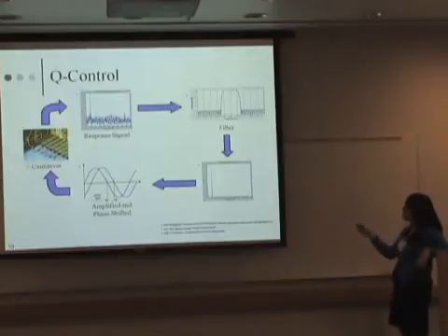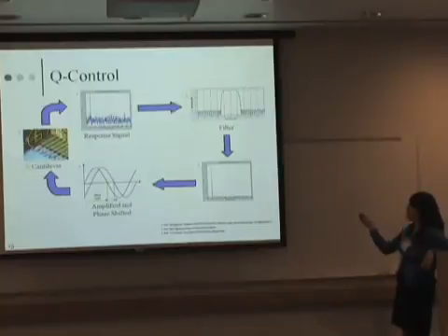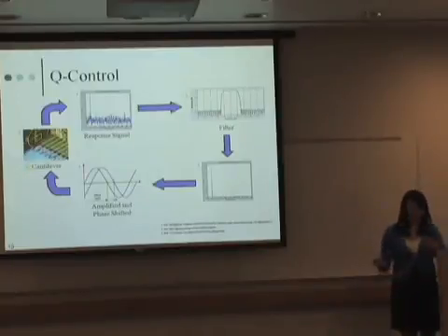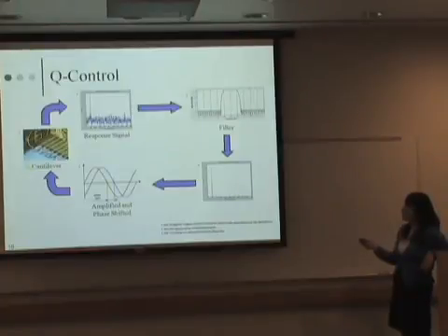So the frequencies that start here and go to here, those are the frequencies we want to keep. So the data that's between those frequencies stays, but all the other frequencies outside of that range are eliminated. So we isolate just the natural frequency of the cantilever. So after it goes through the filter, the graph looks like this. So you notice all this noise right here is just taken out, and you only leave the peak.